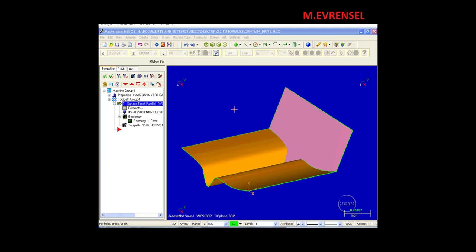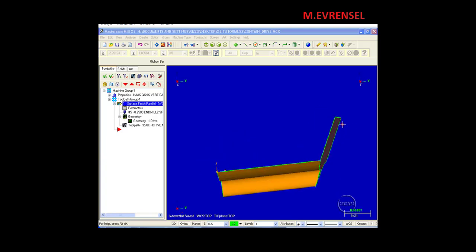In this video, we'll take a look at some basic applications and definitions of drive and check surfaces and containment boundaries. Now, a surface can be either a two-dimensional or three-dimensional entity type generated from curves and used to describe the skin or interior features of a part. Now, this pink surface back here would be an example of a two-dimensional surface. It's basically a flat plane.